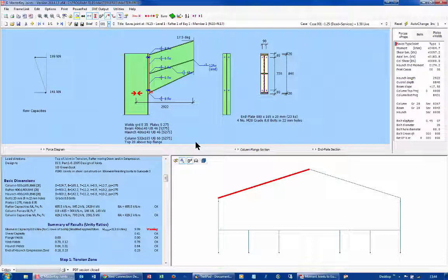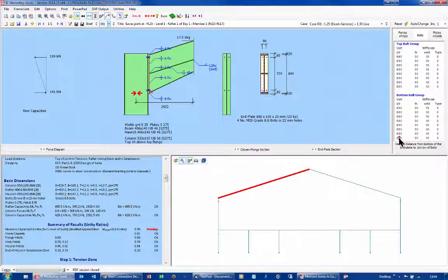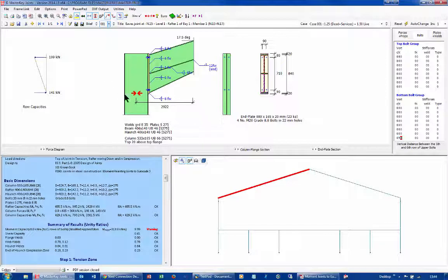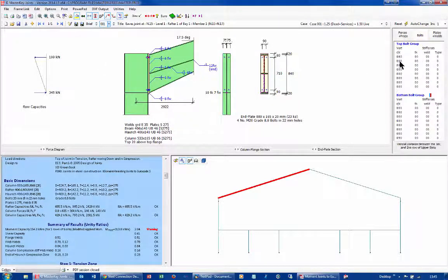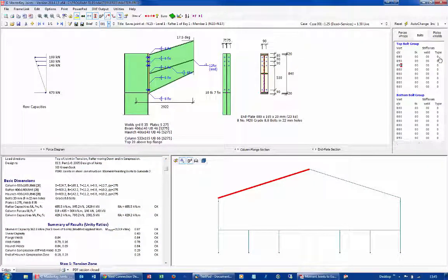But the first thing is geometry, bolts. Move that up to 90 and it now fits, but we're failing miserably. Let's get some more bolts in and let's get some compression in here very quickly. Bottom, and now let's put some more bolts in, and we go 90 and 90 and done. And as I said, that is the first of, in this case, two loading cases, because I didn't bother with wind analysis on this. I was just trying to get some basic simple stuff.